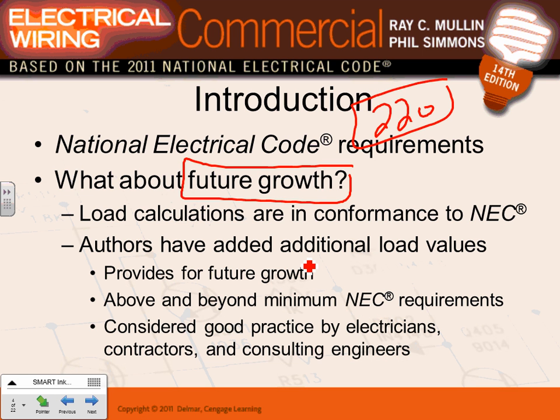If you guys look at load calculation here, a good design rule is to allow 10% growth on branch circuits and feeders. So what I would like you guys to do, not the service though, is allow it on feeders and branch circuits. Can you guys take this into consideration? 10% growth on feeders and branch circuits. This is on page 4, circled. Did I give you guys page 4 circled? Please pay attention to it.